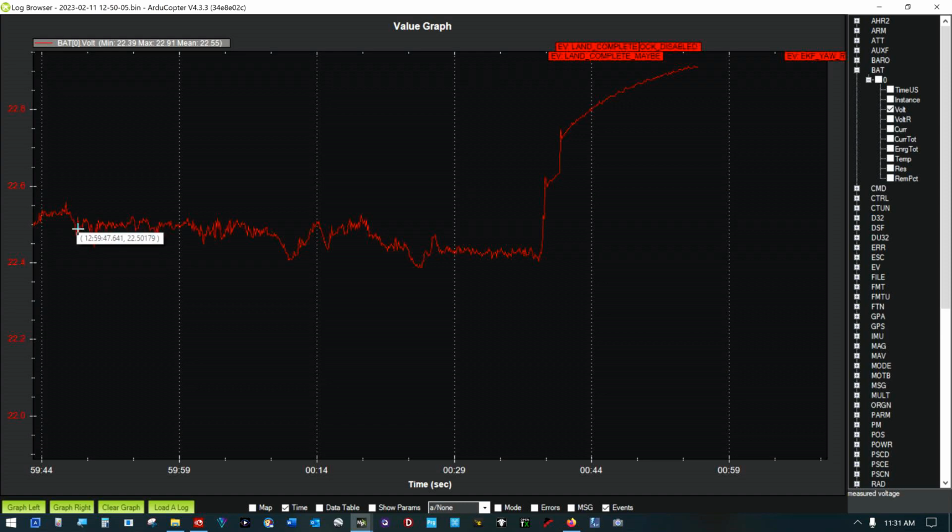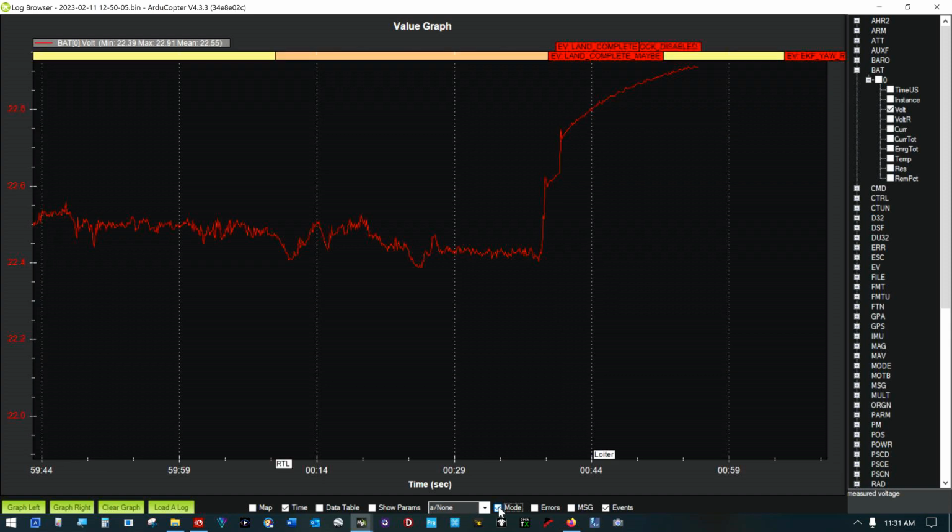Right there it is. And right there it goes low for the first time, below 22.5 volts. The little problem here is there's a 10-second timeout on that. It has to stay there for 10 seconds. And you can see right here where this graph is flat. I brought it over near return to launch, got it down low, and I can see now it didn't fail safe, because there would be a message straight up above.